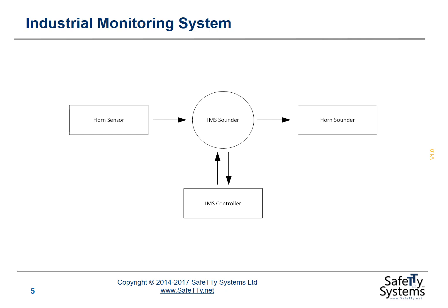So the sounder unit talks to the IMS controller and sends status messages back to the IMS controller. Its fundamental job, though, is to control the sounder itself and to receive feedback from the sounder. So basically it's supposed to turn on this horn and then be sure that once it's turned on, the horn has actually been activated. And that's the simple job that's the responsibility of this sounder unit.